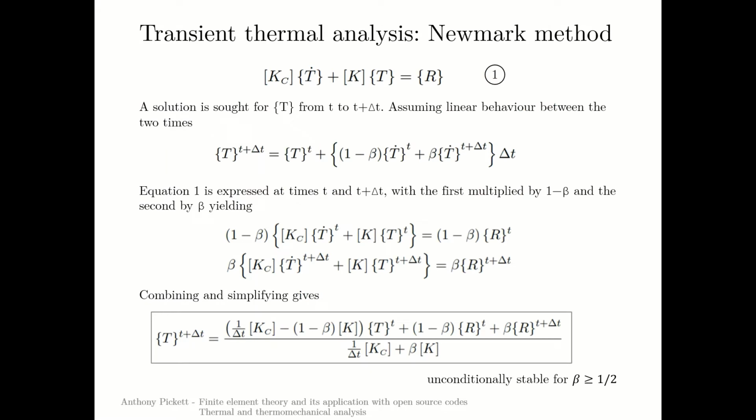One of the analyses I will be doing will be a transient analysis, which predicts how temperature changes with time as heat flows through a component. In this case, the set of equations governing the problem is given here. These are our flow equations. This is our standard conduction and nodal temperature equations. And this is the capacitance and the time-dependent temperature. And this is the part that's giving a time dependence to the solution.